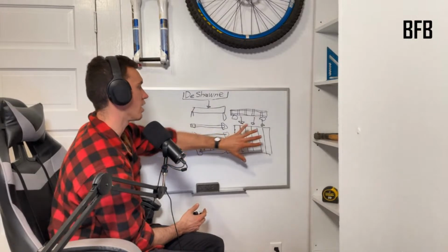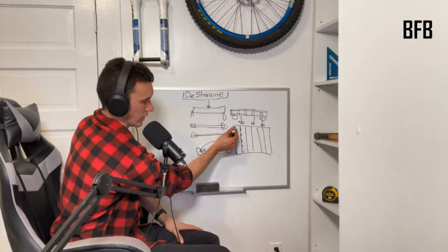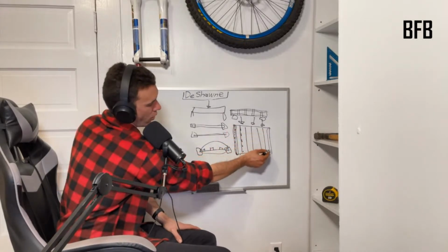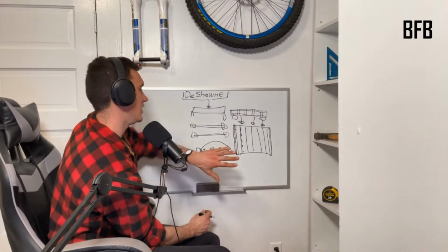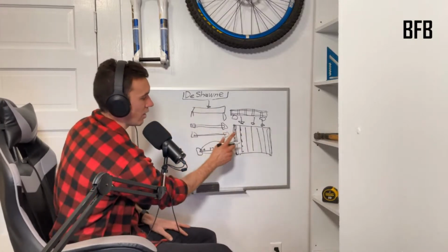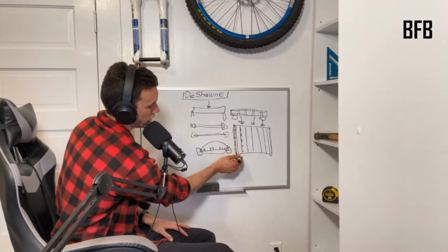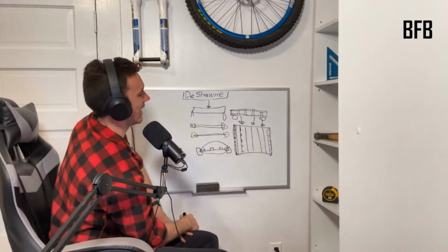What if we set our ceiling on some walls? There's a wall below that one and a wall below that one. Okay. Now the ceiling is sitting on walls, and not only is it sitting on walls, but we're going to nail that ceiling joist down to the top plate of the wall so it can't go anywhere.